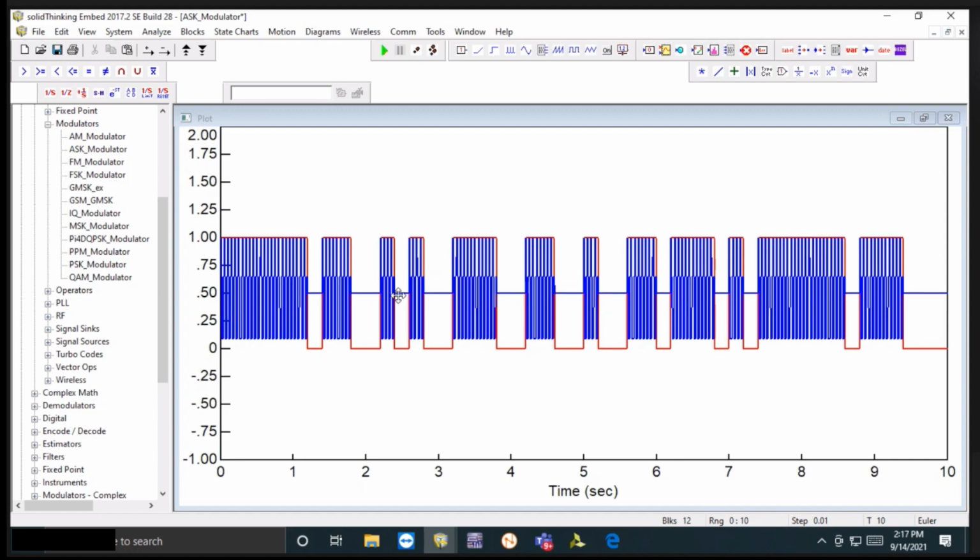Actually, there is a phase shift of 180 degrees, changing its phase by 180 degrees and making it cosinusoidal to minus cosinusoidal. Previously, it was cosinusoidal, then we have minus cosinusoidal. What does it mean? It means that whenever there is a transition, we'll multiply the carrier signal with 1 or minus 1. Actually minus 1, because previously it was cosinusoidal. We'll multiply it with minus 1, it will become minus cosinusoidal.